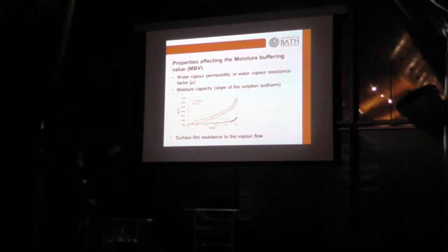As an example, there's two different clay minerals. So there's kaolinite and montmorillonite. Montmorillonite is a smectite type, and this is its moisture content in percentage per relative humidity. So you can see that the two behave completely differently. Most of the soils are probably more like the kaolinite at the bottom. But there is a variation between these different clays.